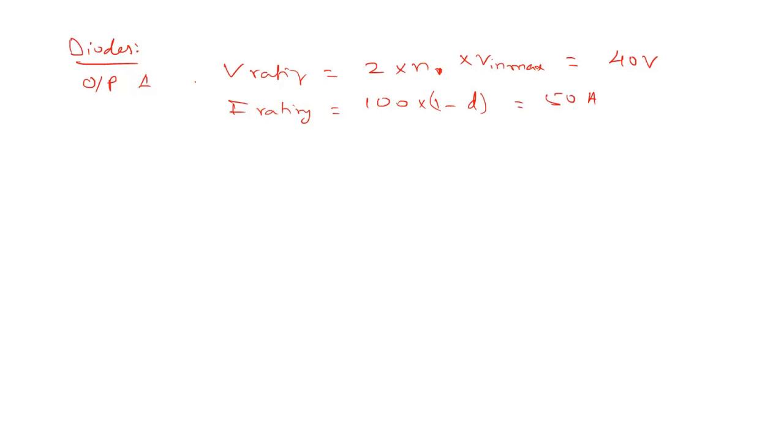Okay, or probably an easier way to say this is 100 amperes total current, and the diodes share the current equally, so that's 100 over 2, also 50 amperes. Either way is fine. And of course I peak is the same as the MOSFET, since it's on the secondary side. So I peak, you can write it explicitly for the diode, is also 105 amperes.